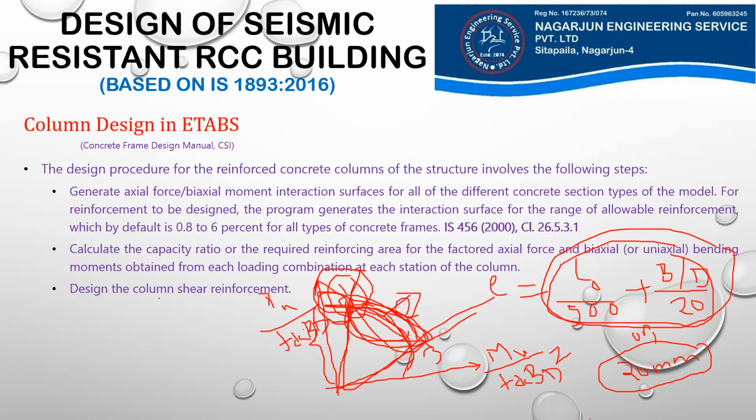And in this region we see that, let me draw this once again here. So this second region is the axial load carrying capacity in the y direction. We see that if we travel from this point to this point here, the axial load carrying capacity decreases, but the bending moment carrying capacity increases. So in the compression control region, both forces are dominating.